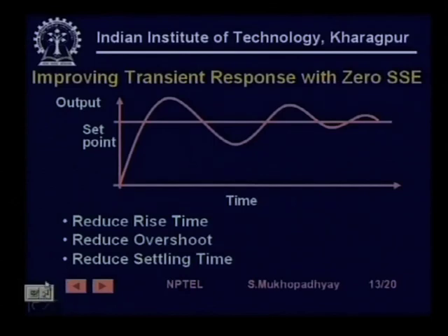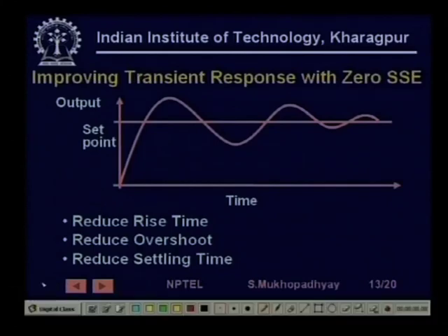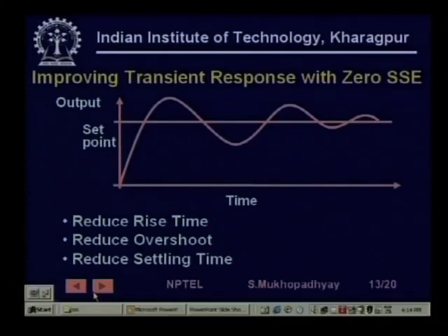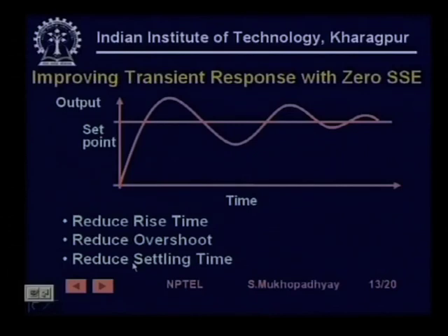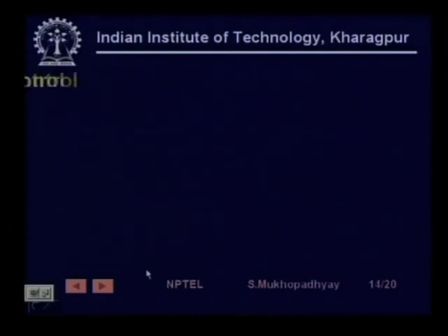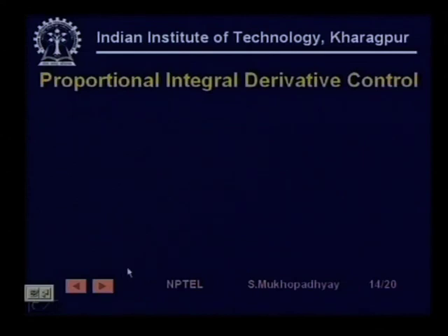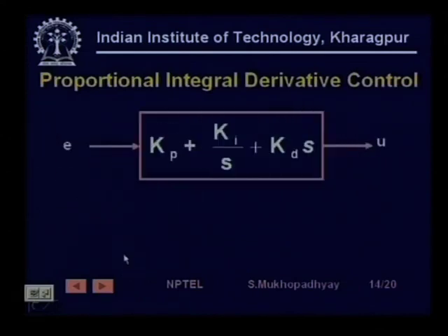Now, getting all this is somewhat difficult, and that is why you need a non-trivial tuning exercise to come to a compromise between these. We have already discussed proportional and integral controller, and we have also seen that adding a derivative will try to brake so that it does not go towards much overshoot.